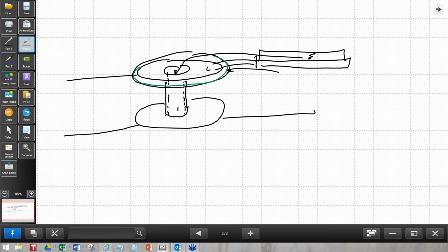So basically, outside the hole, we need to leave the pad uncovered. We may want to leave the via uncovered, but it's necessary to put solder mask outside of it. All right, that's great. So the first question comes, how far away from this should it be? How far should the solder mask be from the hole?